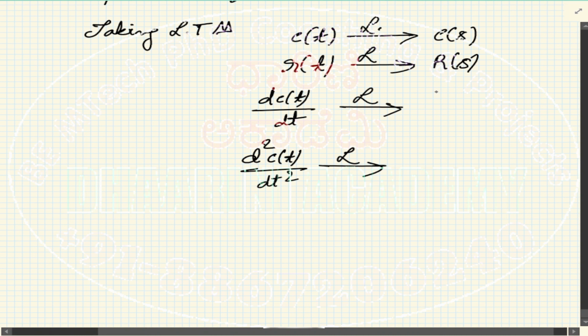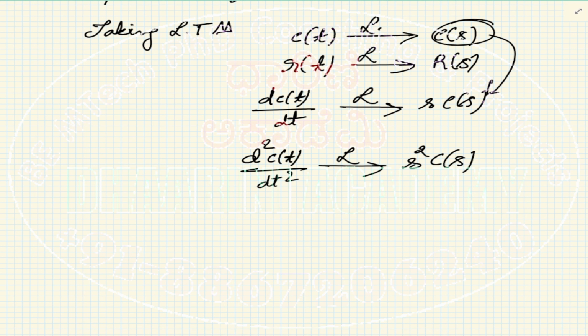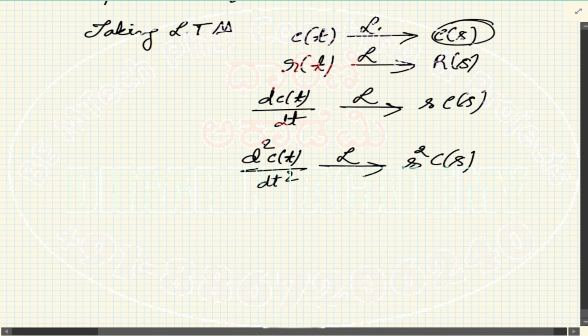Okay, no problem. Anyway, I think in the requirement you sent there is one whole chapter called Laplace transform. Correct? Okay, we'll discuss in detail over there. Now I'll tell you the answer. This is simply multiplication by s, s into c of s. So double differentiation generates an s square into c of s. Whatever is the c of s, it comes over there with the multiplication of s. So the number of times you have differentiation, the same number of times you get multiplied by s.